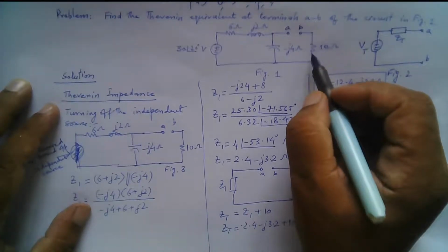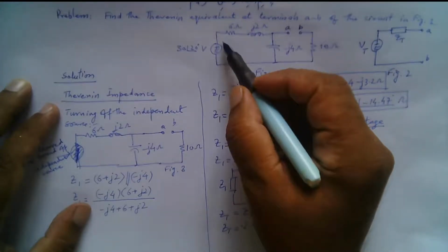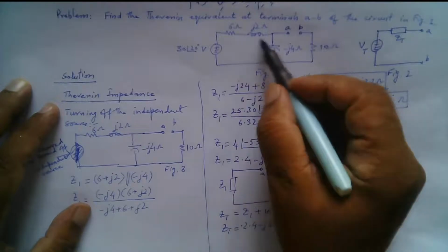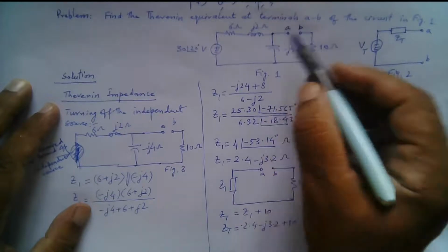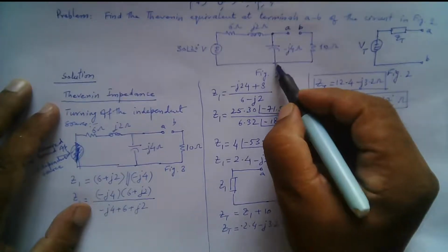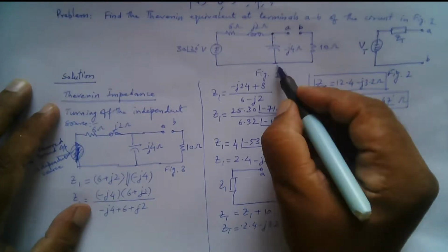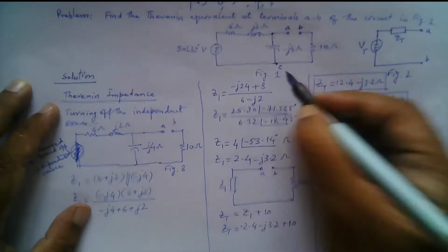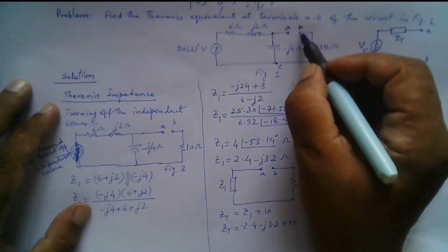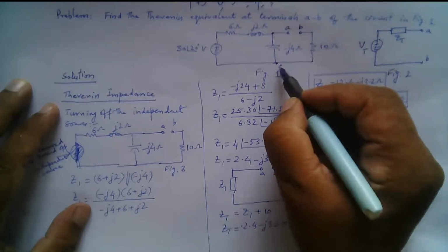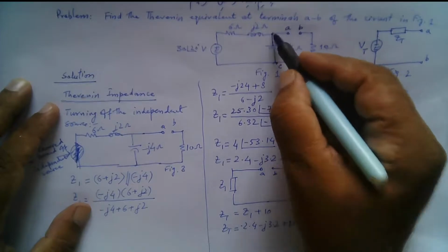Across this resistance, the current flows like this from the voltage source through this branch and then through this branch, and the voltage here at terminal A is the same as the voltage across E and B here. For example, if this is point B, let's call this point C. As there is no potential drop across this resistance, the potential here is the same as the potential here, right? So the voltage VAB is the same as the voltage VAC.